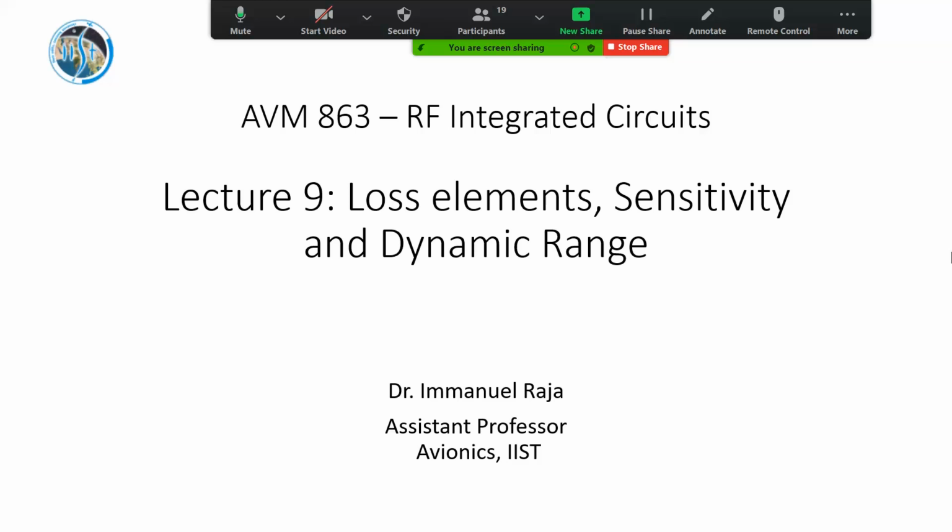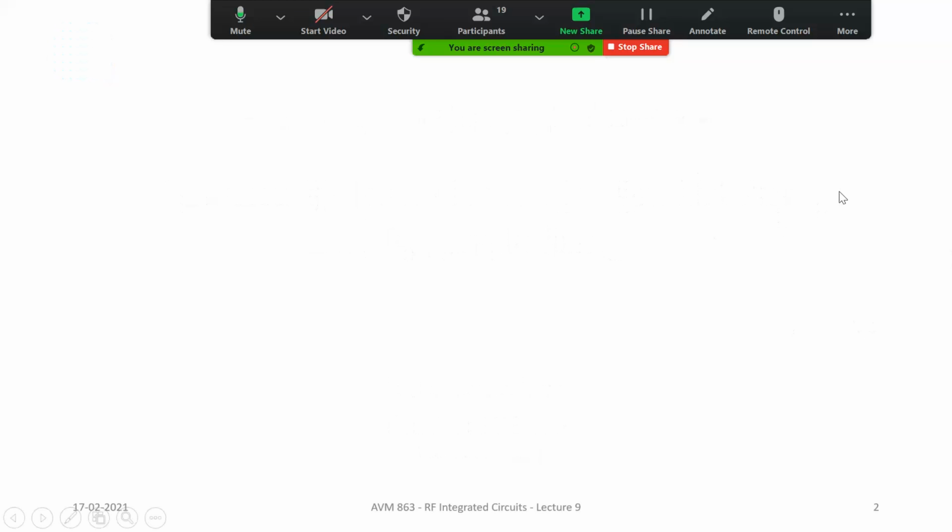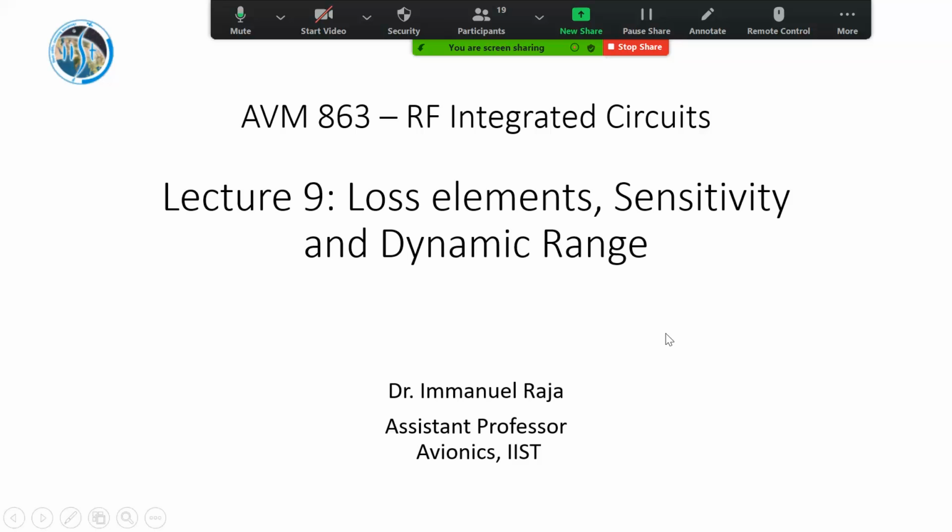So we looked at both extremes now, right? We looked at one extreme, which is when you have very large signals, you end up with non-linearity. You have distortion, intermodulation, and all those non-linear effects. Then we came to the other extreme, where you don't have much signal. I mean, your signal swing and everything is extremely limited. So you are now basically fighting with noise, right? That is the range to which we have come now, and we looked at noise figure and other things.